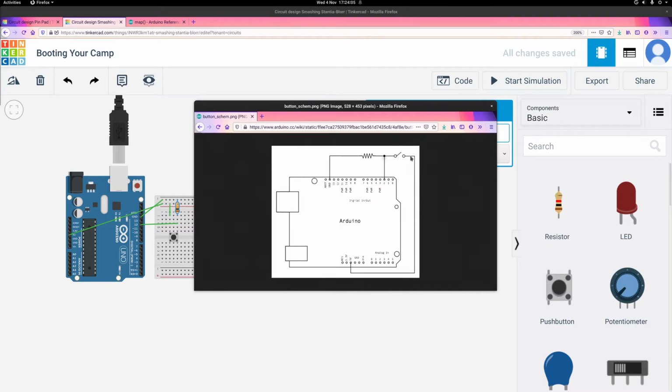But when the switch is closed, it's also connected to this high 5 volts. And now, because this 5 volt line does not have any resistor on it, it overpowers this low voltage that's hidden behind this resistor. So the overall voltage at this particular point becomes a high voltage because current flows this way, and the voltage is dropped across the resistor. So over here it's low, but it has to be high on this side of the resistor because the voltage is dropping. So we'll read a high voltage there.